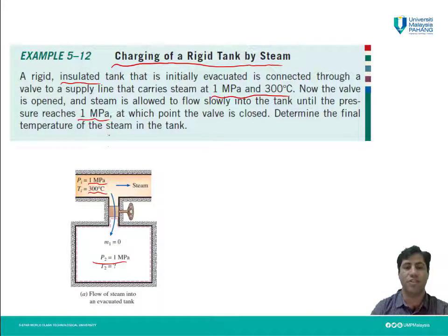Or it is mentioned that we open the valve, we give enough time until the pressure inside the tank reaches 1 megapascal. Then we close the valve. What we need to determine is the final temperature of the steam inside the tank. The steam in the line is 300 degrees Celsius, but the temperature inside the tank, we don't know how much it is. Then how can we calculate it?